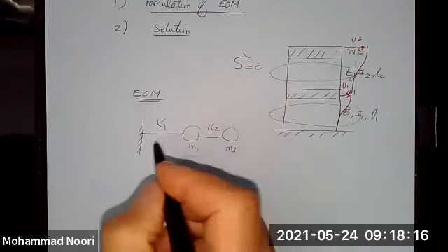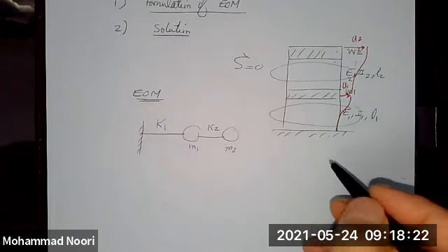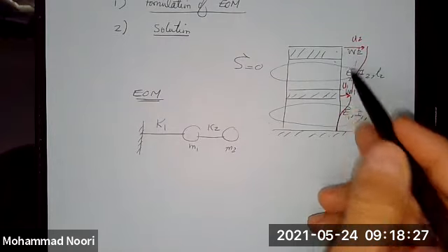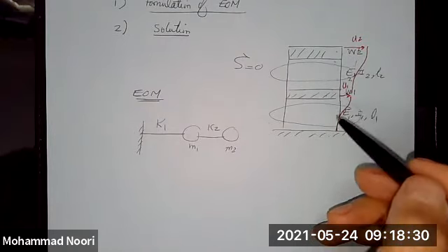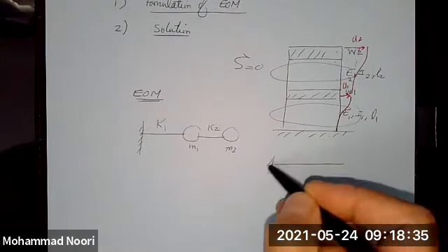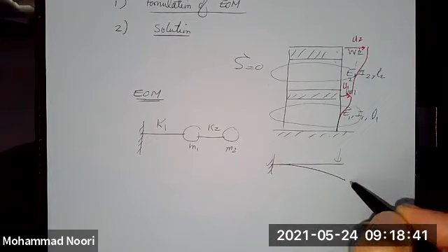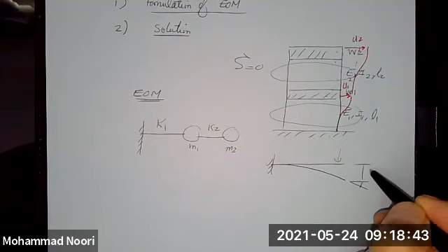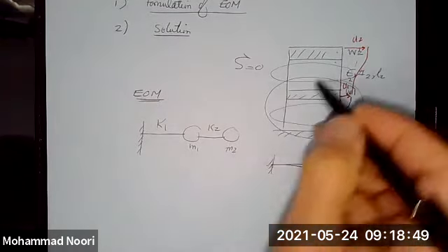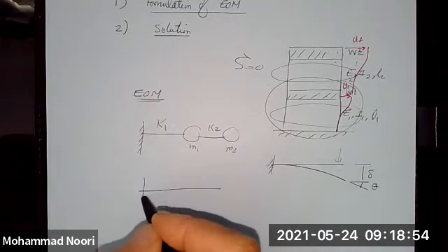The way this system is moving, okay, is different from a cantilever beam. As I said, there is no rotation allowed at this point of connections. In a cantilever beam, when you had a displacement due to a load here, it moves like this, right? So you have both rotation and displacement. In this case, look at, for instance, here, what you have is an indeterminate structure.